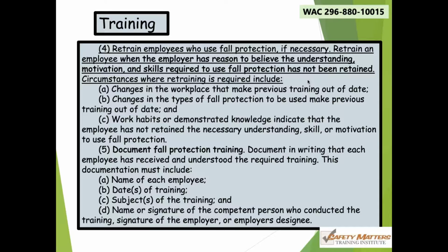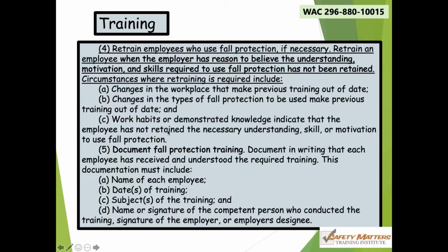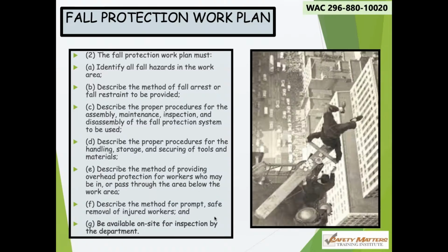Of course, we always have to document fall protection, right? So document, document, document. Look at what they say here in documentation though. Make sure you're including the name of the employee, the dates you trained them, the subjects you trained them, and then the name and the signature of the competent person who actually conducted that training. No real big changes to the fall protection work plan. They just changed and clarified the definition of it.